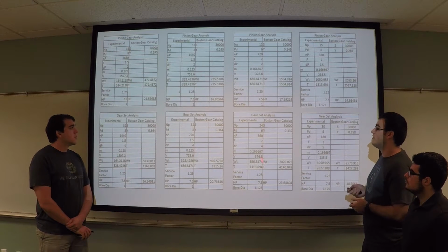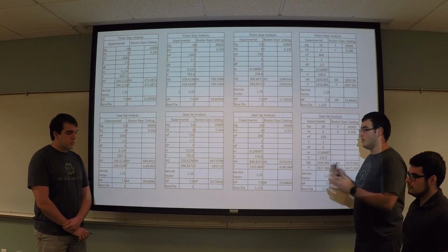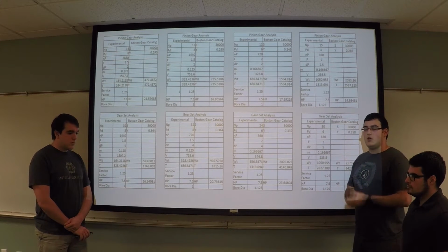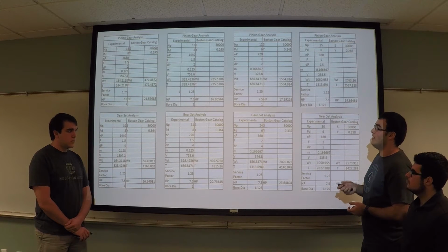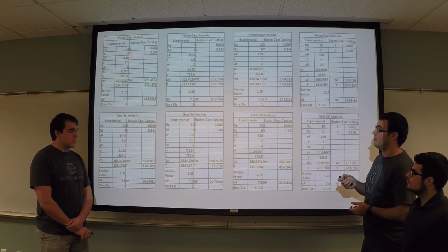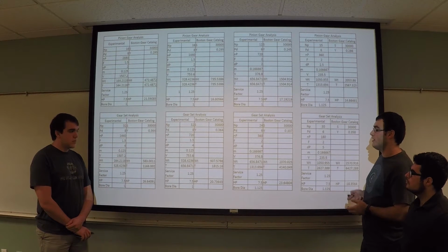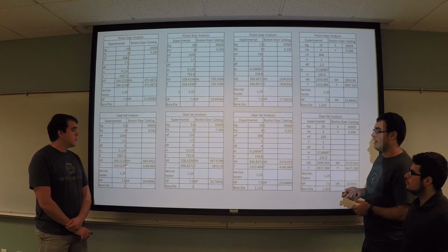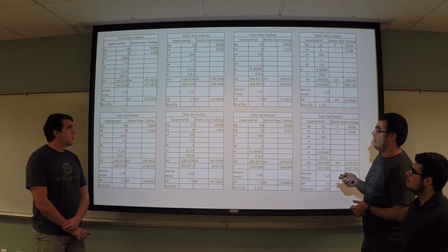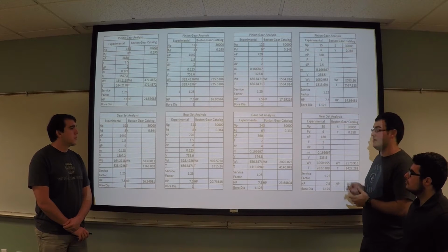Since we have 4 stages, the overall gear ratio of this transmission or this gear train would be 16:1. As you can see, as the speed reduces, as the amount of revolutions reduces from gear stage to gear stage, it can be seen that the torque being applied is increasing as the gears increase in stages.